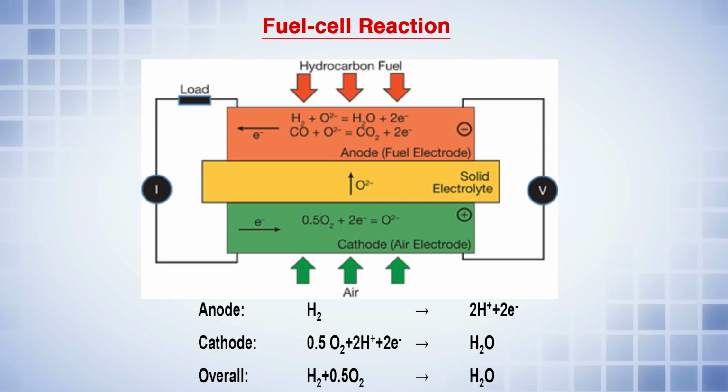No doubt the voltage of the fuel cell is very low. That is why we increase the voltage by putting a DC-DC converter in between the load and the fuel cell, in order to get the boosted voltage and meet the requirement of the load. So here you can see those kinds of reactions.